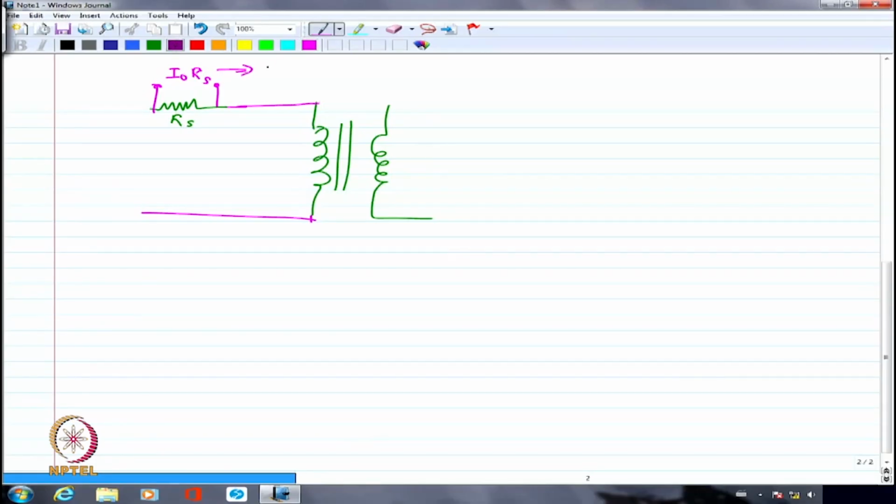So this will obviously go to the x-axis of the plotting of B versus H. If I want to plot, I will give this to the x-axis or x-plates of the CRO. Right? That's what we were doing. If you may recall, this will go to the x-plates of the CRO. So I will put the CRO in XY plot mode. Now what I want is the flux. The flux has to go to the Y plate.